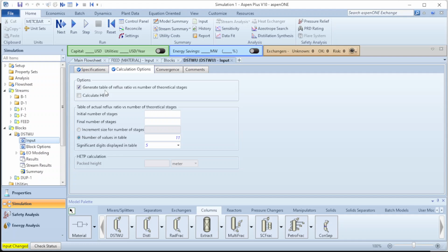And I'll explain that one to you. So what you have to note is that with a higher reflux ratio, the column has to have higher liquid load. Once the reflux ratio is high, there will be high liquid load and the column diameter will increase. And as the column diameter increases, you will see that the energy duty for both condenser and reboiler needs to increase for us to achieve our desired separation.